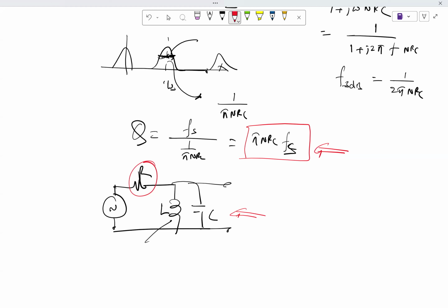If you want these things to work at higher frequencies, the clock has to be higher frequency, and that's a genuine problem. So these types of filters do not work very well at higher frequencies. What counts as higher depends on technology, but typically a few gigahertz is fine in modern technologies. If you want to go to tens of gigahertz, it's not a very good solution. That's a practical aspect of it. We'll be limited by clocking.